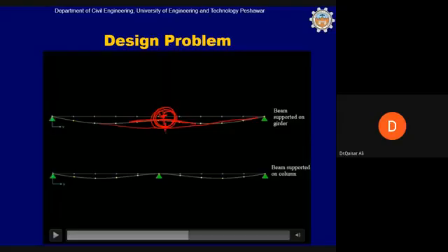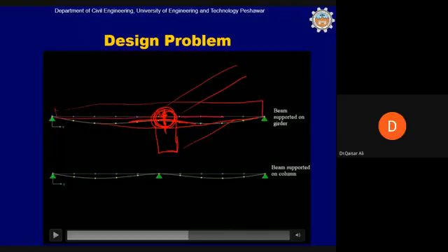So this elastic curve can come like this, because the beam and the girder both will come down. In order to keep this up, you have to provide a deep girder here, because the beam is being rested by this girder, which is this girder, and this is the beam. The beam is coming like this on this. So the location where the beam is supported by the girder must be stiff enough to minimize the deflection of the beam at this location. Okay.